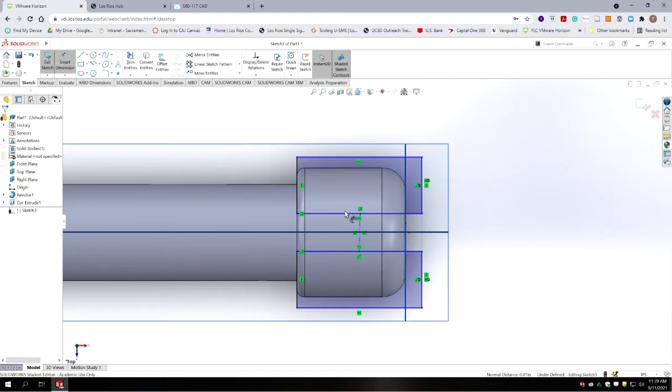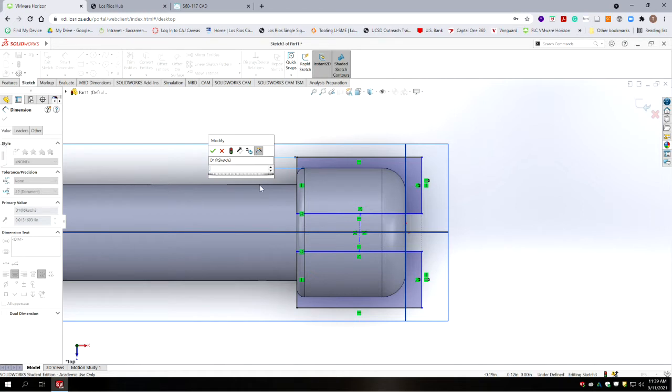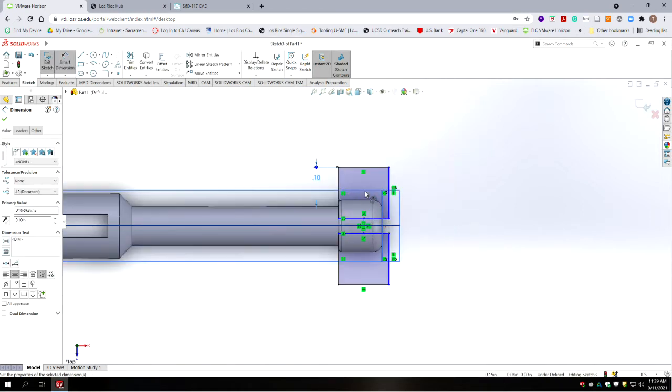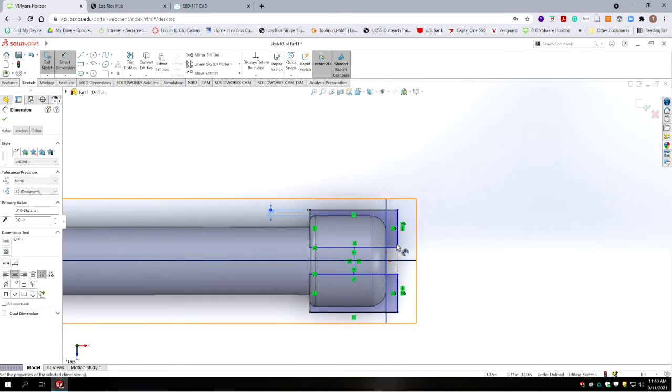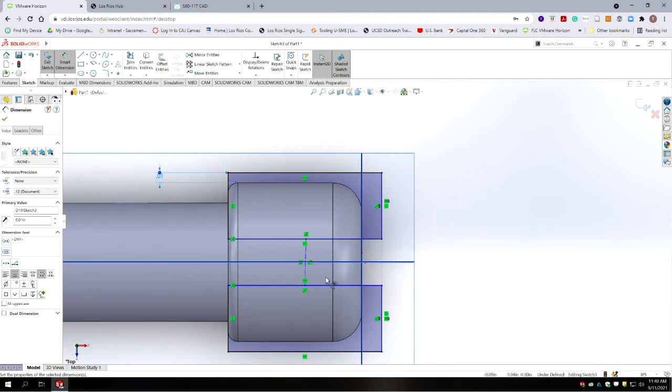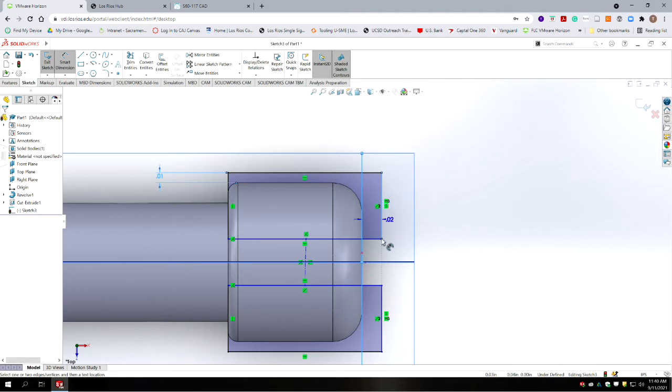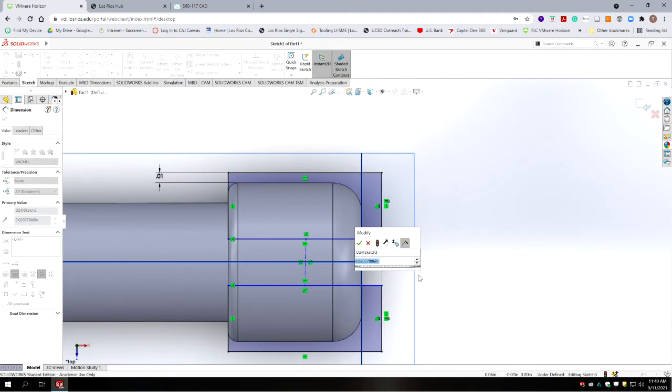Alright, now let's put a length on them. We're going to make sure that no matter what size we make these features, if we measure from the extents of the revolution, we'll go 0.01. If we increase the size of this boss parametrically, it always makes the cut larger, and the same if we change these fillet sizes. We're going to do the same thing with the distance between here and the end of the part. We call it 0.01.